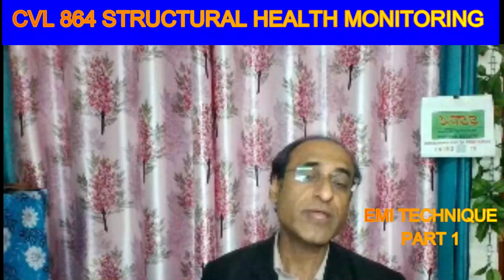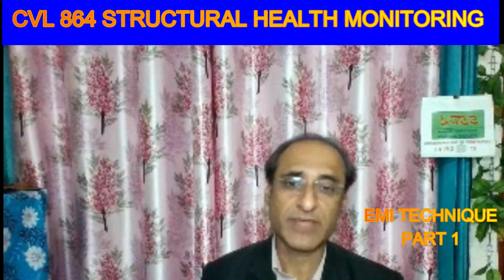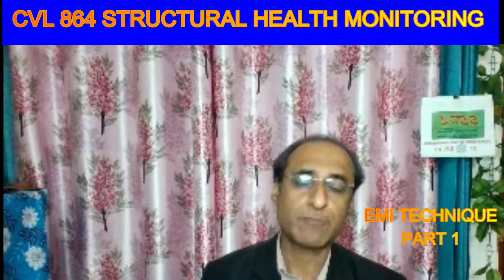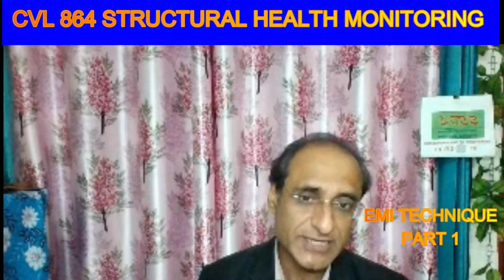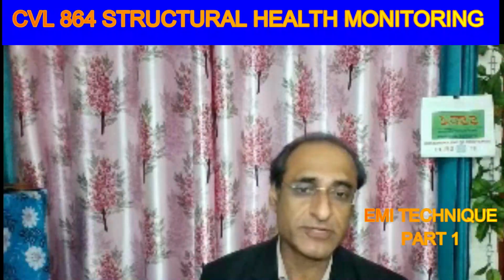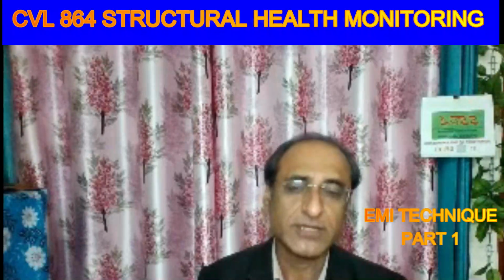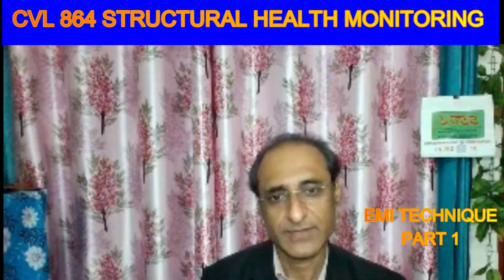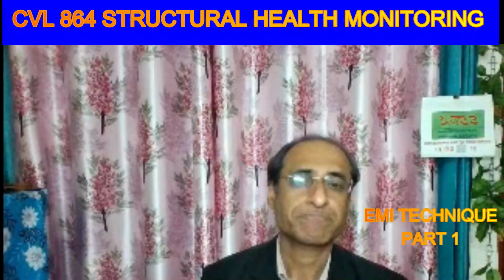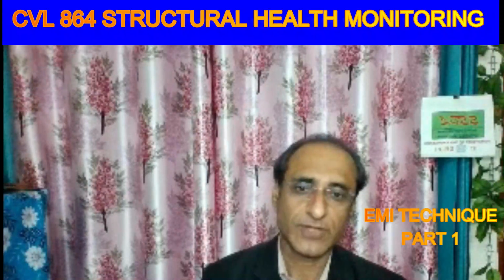And then the other question is, how do we calculate the mechanical impedance of the piezo patch? I give you a hint. How do we define mechanical impedance? We define mechanical impedance as the ratio of force to velocity. So all you have to do is apply force and at that point measure velocity. But velocity measurement is difficult, so in place of velocity, we can measure displacement. Velocity is just the time derivative of displacement, so whatever displacement amplitude you have obtained, you multiply it by omega, and you will get velocity. So we have the applied force, we have the measured velocity, and the ratio will give you the mechanical impedance of the piezo patch.